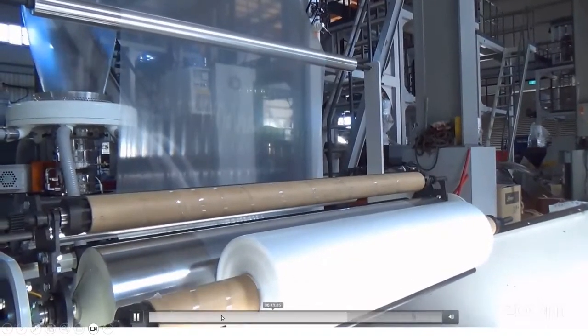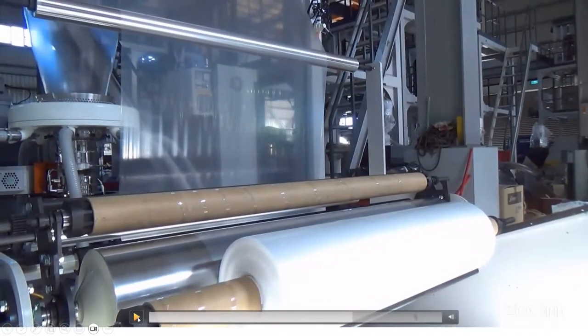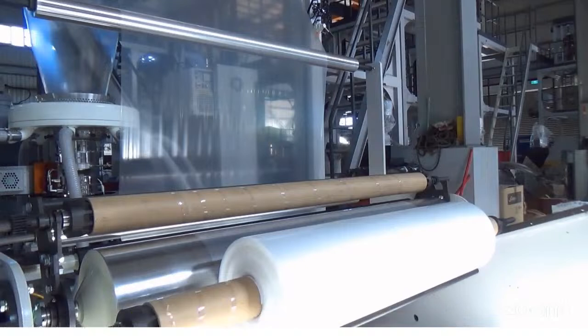See, this is now here. If you see here, this roll is rotating, and this bobbin is only rotating. There is no motor. See, there is no motor here, right? When this roll rotates, that time this roll rotates this way, and this is very good. It is called surface winding, and it is tension free, stress free. You will get a very smooth winding there, friend.